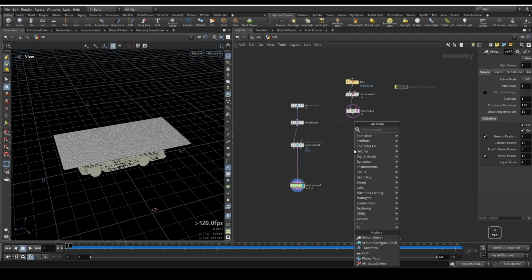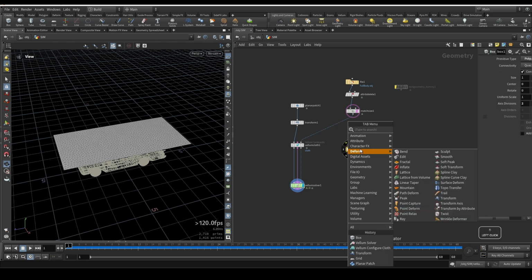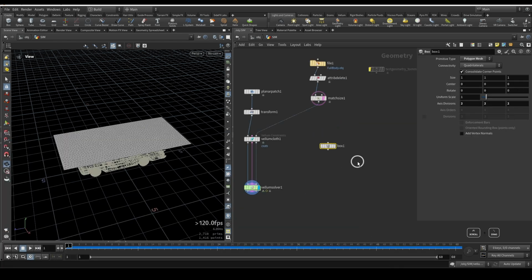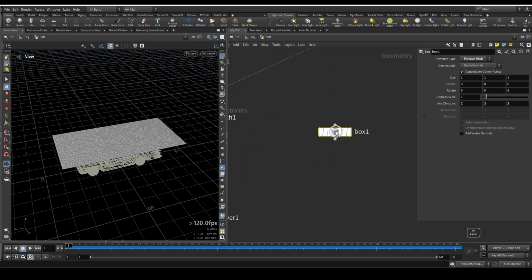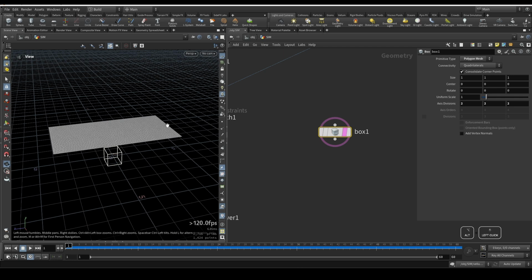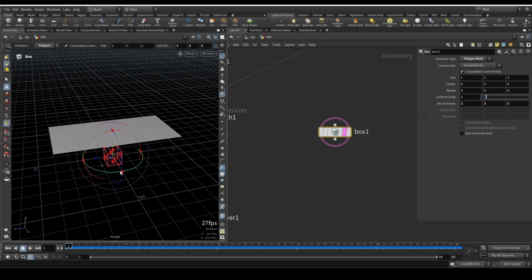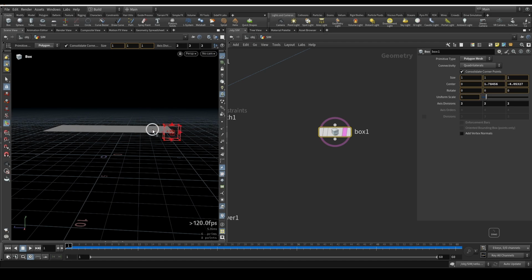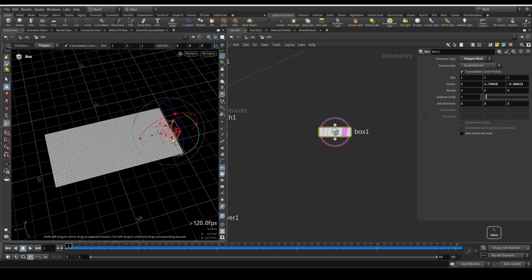So let's take a geometry. Let's take a box. Also, if you search cube, we get a box. So that is a great thought put by Houdini. So once we select here, we have this box. We need to get it to this end. So what we'll do is press enter. So we get these controls, take it here, and quickly let's move it to this section.